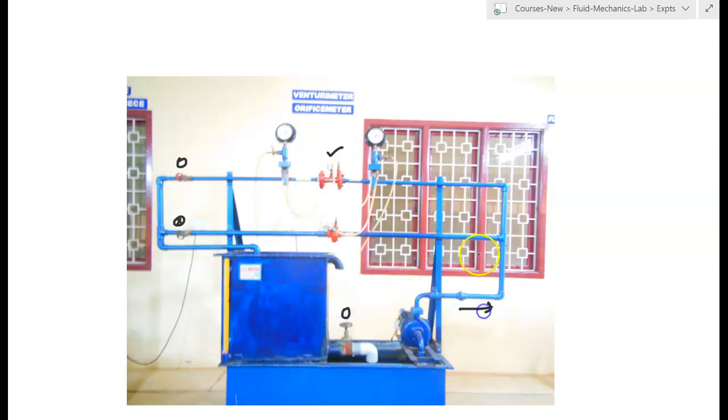So water will flow through this, water will rise here and go through both these pipelines, but because this Orificemeter valve is closed, water will just be stagnant on this line; it will not flow. Whereas water will flow through this Venturi-meter and come to this collecting tank, and from this collecting tank water will flow again to the reservoir.